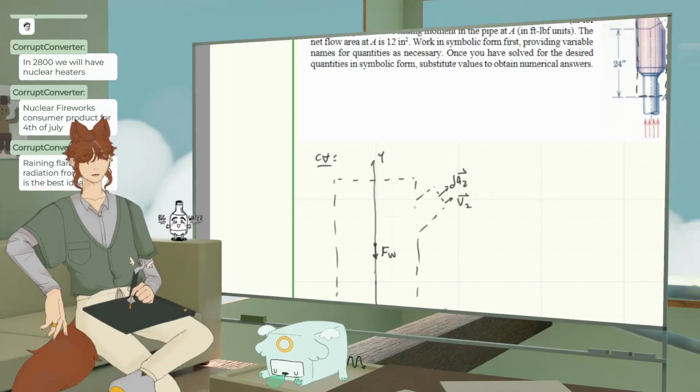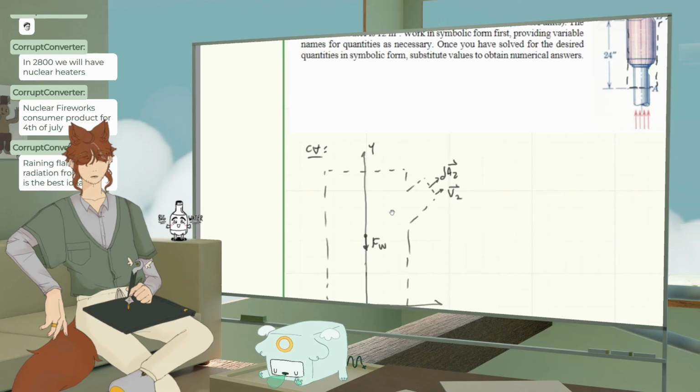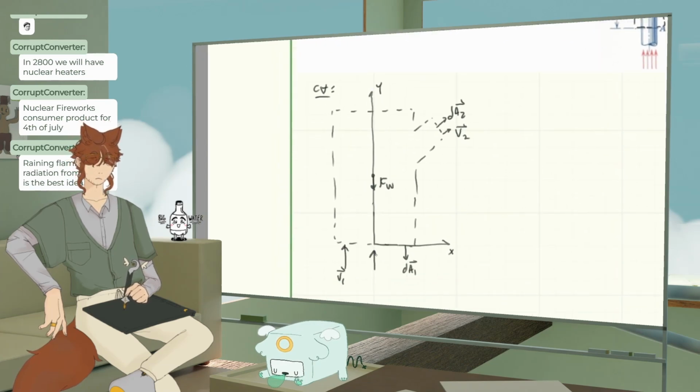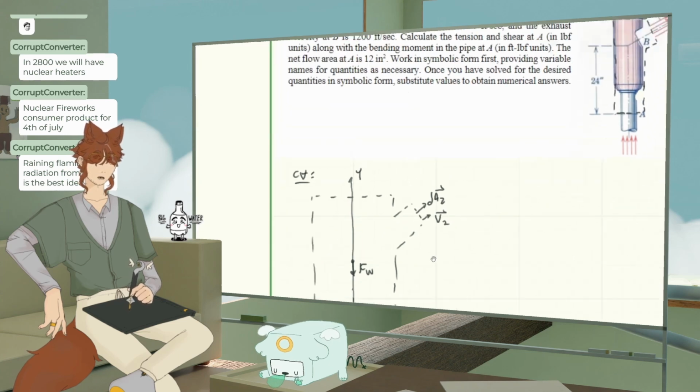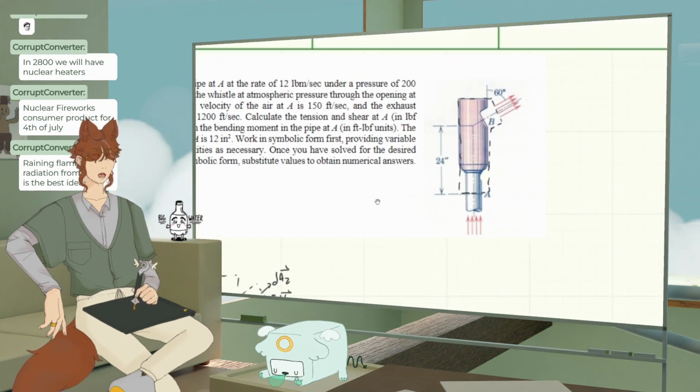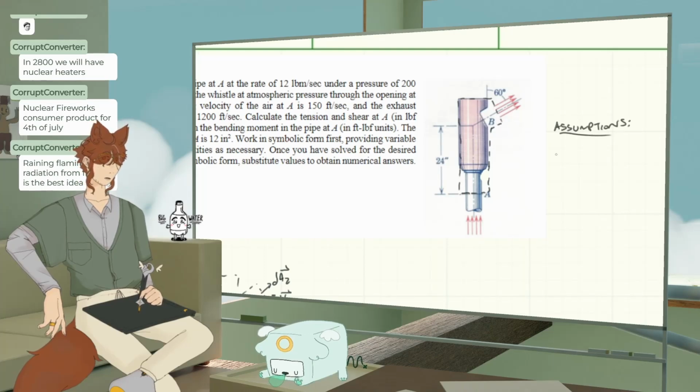So we did that, we're not going to do R vectors yet. We're going to do body forces, we did. Surface forces due to pressure. Okay, there's a pressure force here. It's going to act through the center. No pressure force on the end because it's a free jet. Well, not because it's a free jet, but because they specify, because it is air, so it's not necessarily incompressible. But we can say steady flow. And we can say uniform rho across the CS's.